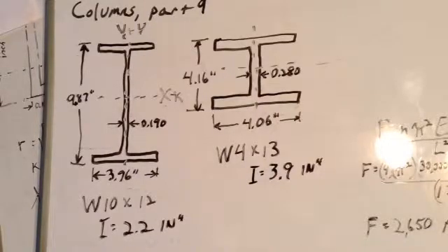As you can see, when choosing beam cross-sections for columns, a choice would ideally be as strong about its x-axis as it is about its y-axis. This is why many columns are round posts or pipes. Of course, we're not going to use these 12 pound per foot beams to build our airplane, but these tables show that certain slenderness ratios mandate certain allowable stresses, regardless of the other characteristics of the beams.